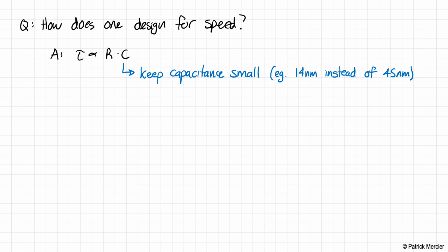So, as designers, we're only limited by whatever the process can give us, other than keeping our design sizes rather small. And interestingly, this poses an optimization problem that we may encounter in homework or something, that basically says that maybe we don't want to optimize our circuits for symmetric voltage transfer curves in the pursuit of trying to achieve as fast of speed as possible.